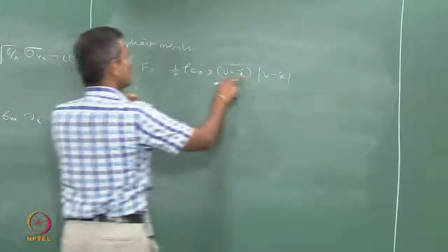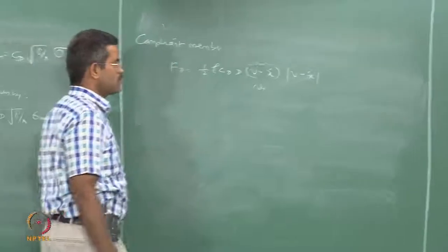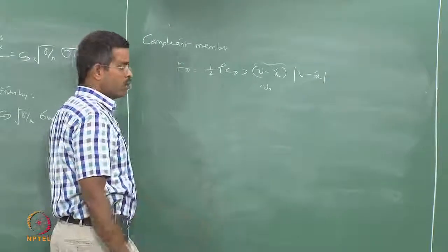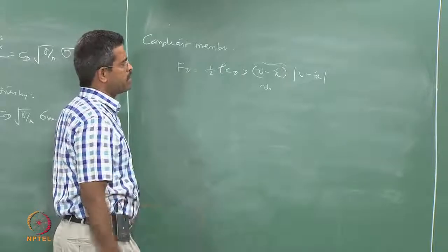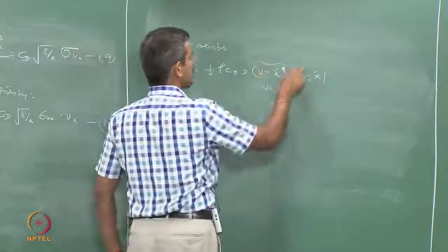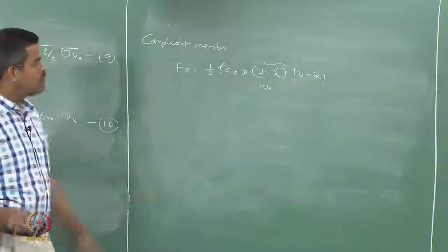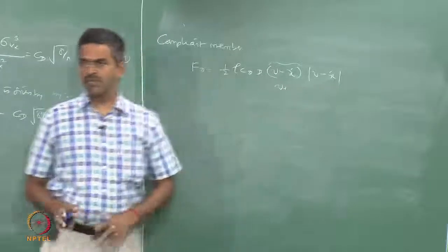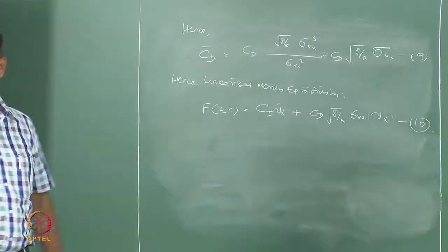If you expand this term and maintain the sign because of the mod on only one of these, you will see there is a square term and a product. There are square terms available at V squared, which is velocity square, structural velocity square, and the product of V and x dot which will become nonlinear, which cannot be computed, because x dot is not known to me, it is the solution of the problem actually.